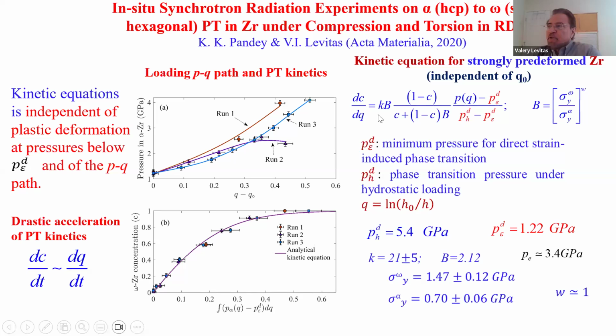we produce multiple rolling until hardness, dislocation density, and crystallite size reach a steady value and don't change anymore. This is crucial because we just exclude them as controlling parameters, which simplifies the problem drastically. Without this, we could not get any rule. Everything is a complete mess.